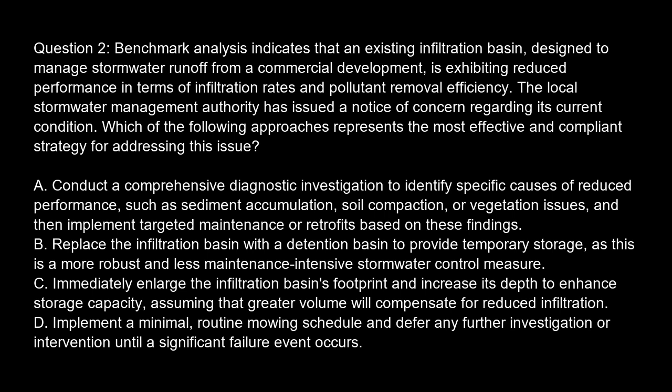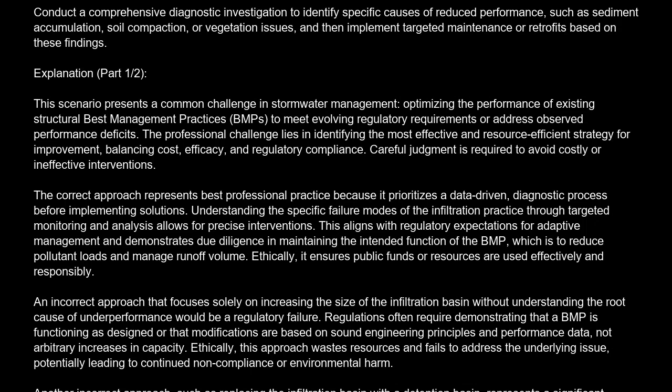Option D. Implement a minimal, routine mowing schedule and defer any further investigation or intervention until a significant failure event occurs. The correct answer is A. Conduct a comprehensive diagnostic investigation to identify specific causes of reduced performance, such as sediment accumulation, soil compaction, or vegetation issues, and then implement targeted maintenance or retrofits based on these findings.